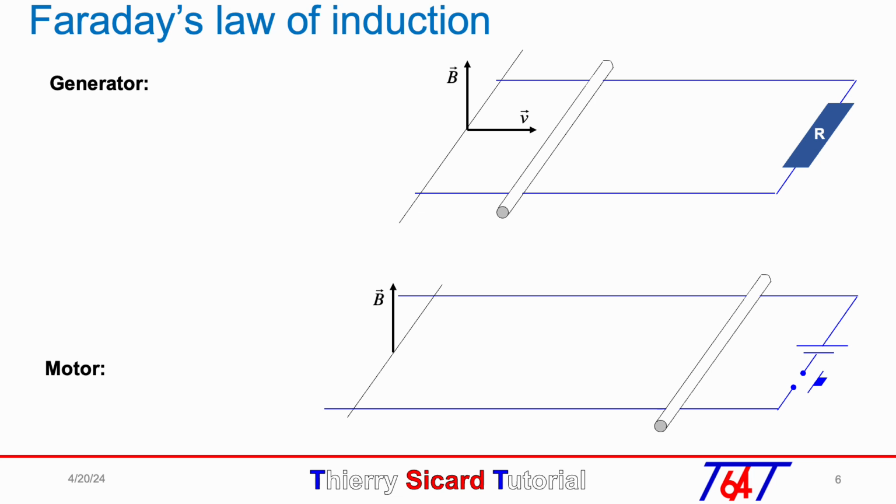If we move the metallic rod to the right, electric charges will have a velocity directed to the right and perpendicular to the vector B. Those moving charges in the magnetic field B will create an electromagnetic field EM, and so a force QEM. Of course, the force QEM will have an effect only on the free moving charges like the electrons. As by definition the conventional current is in the opposite direction of the electrons, a current will pass as shown in